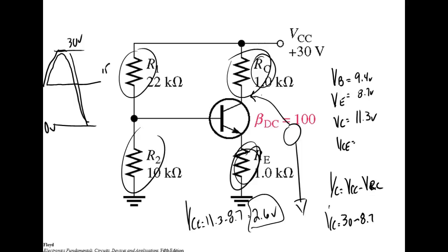So this is my input right here. Here's my transistor, and it's a 3904. The 3904 goes emitter to the left, base in the center, collector to the right. So here's my 100K hooked up to power. Here's my 10K, and it's connected to the base. Here's the 1K. It's connected to my emitter.